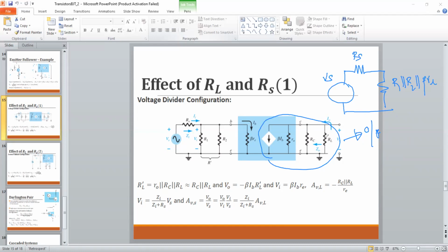So keep in mind there are two gains you can easily evaluate. One is this no load voltage gain. For this case, your load is simply zero, so you don't have any load connected to the output. It's just open. Again, you can evaluate a voltage gain with a load. So it's like the loaded voltage gain, a function of RL and RC. So keep in mind, if you do not match your impedances properly, your gain is simply reduced, because for this kind of scenario, your gain is a function of RL, RC, and RE.